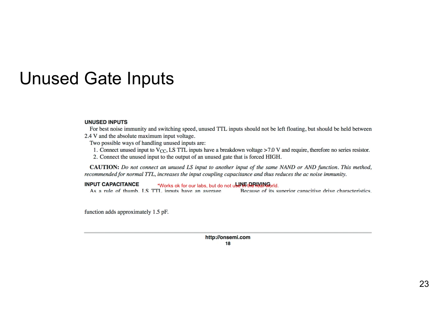Okay, unused gates. It depends on what the function, the logic family is. But this is from the old TTL series, and it says TTL series inputs should not be left floating, but they should be tied somewhere.